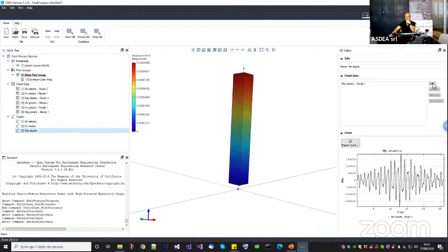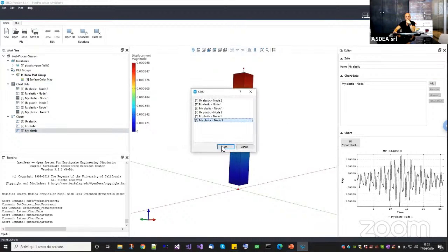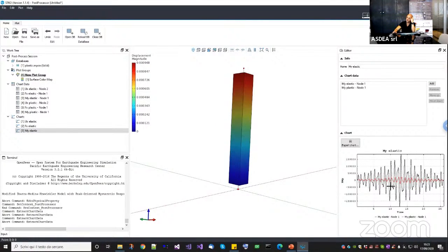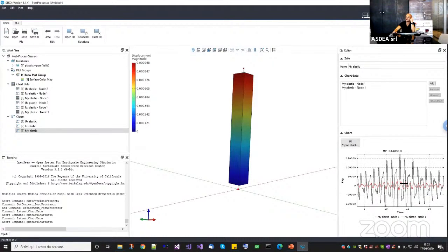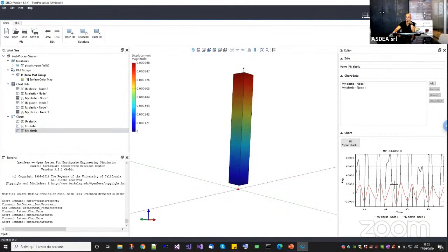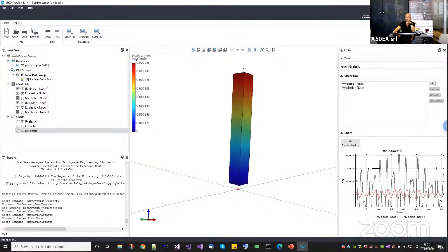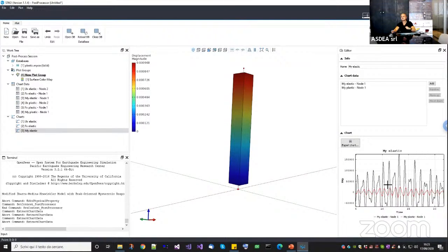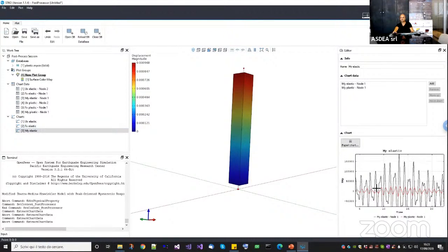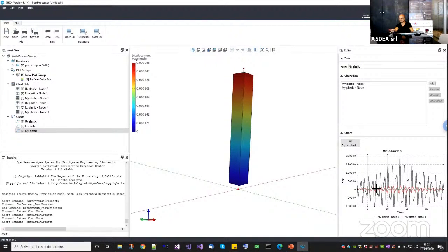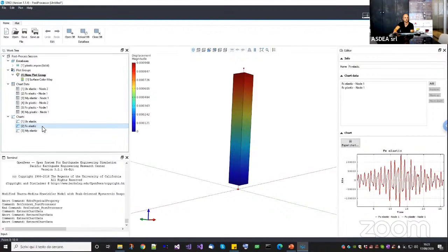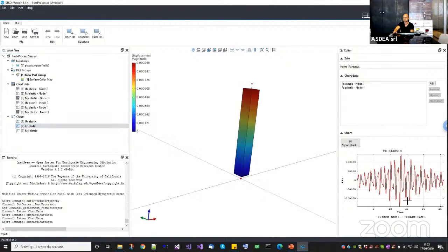So I go here, I superimpose, I expect them to be elastic. But as you can see here, the reaction moments are very, very low, and they didn't even reach the yield stiffness. So you may think, okay, my model remained elastic, but it doesn't make sense, because as I told you, the bending moment, even if your model is elastic or plastic, the equilibrium is always the equilibrium. So the reaction moment should be, in this case, equal to the reaction forces times half of the height of this column. And in this case, it doesn't happen.